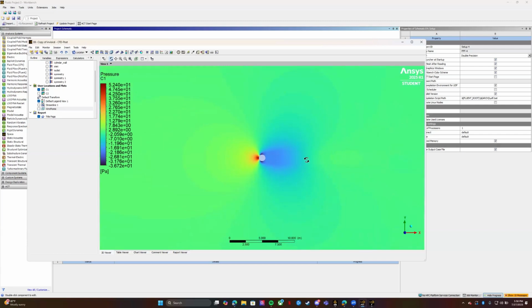So that's a better way to look at it. There's a little bit better. This time we went for Reynolds number 120. We used 0.083 for our viscosity and kept the 10 meters per second. This way we got a little bit better profile for the visuals.